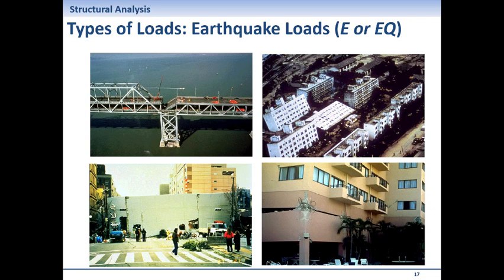And sometimes you see buildings similar to that. It seems like an intact building, just too tired to stand and lying down. That's because it's sitting on sandy soil, and that liquefaction has happened. Over a few seconds it may just happen. And then it's like you've got a building in a pool. So it just becomes like that. And you can see a few of them have had the same experience. The same thing has happened here.